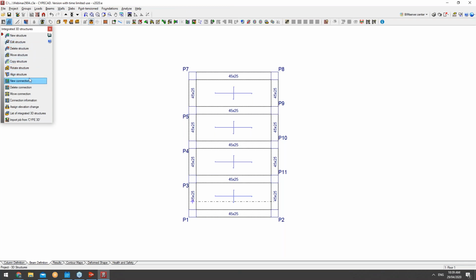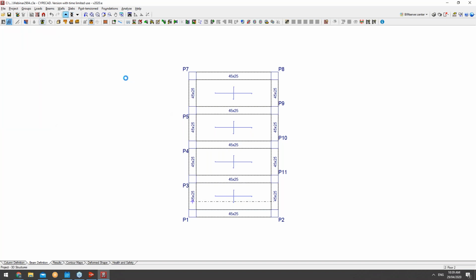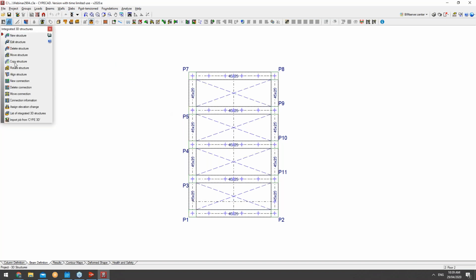Of course, what I wanted to show as well was the connection information. We can come over here and look at all the different connections. So I can see the position, the elevation, and the absolute level as well. Upon moving over as well, I can view the different information for my steel structure on the top. So for all the different nodes that I've introduced, I'm able to obtain connection information from those particular nodes.